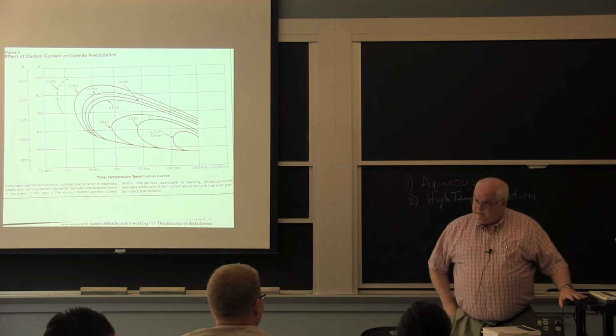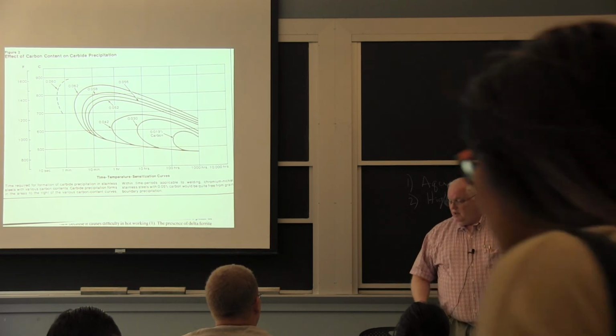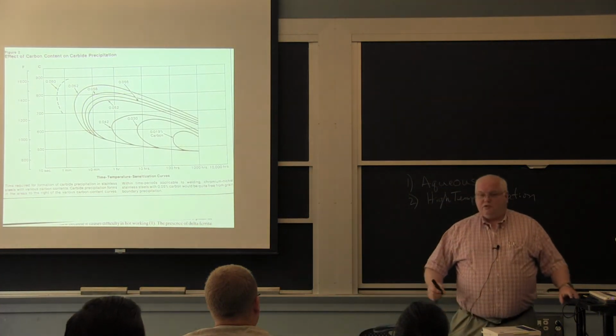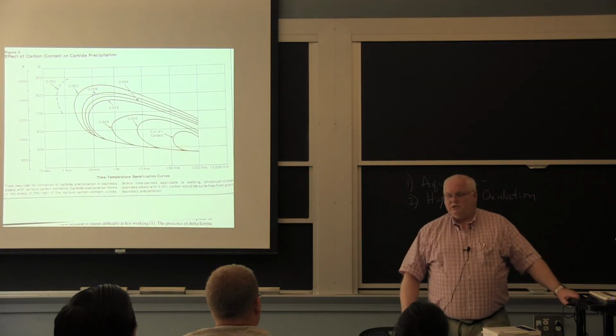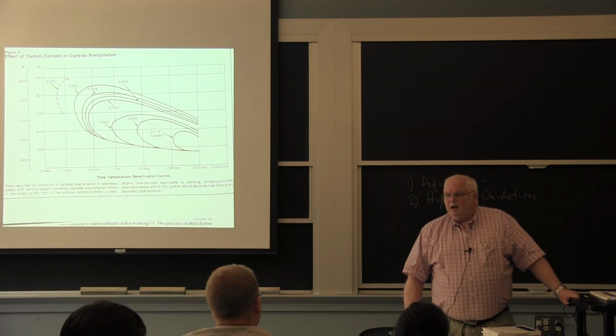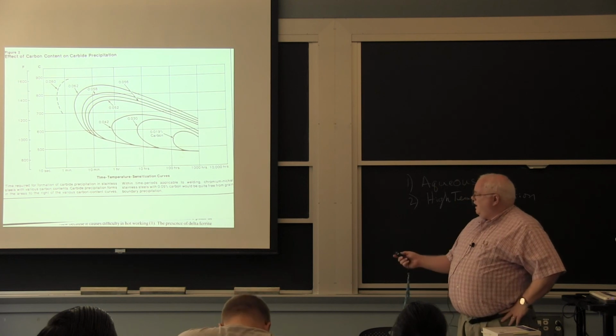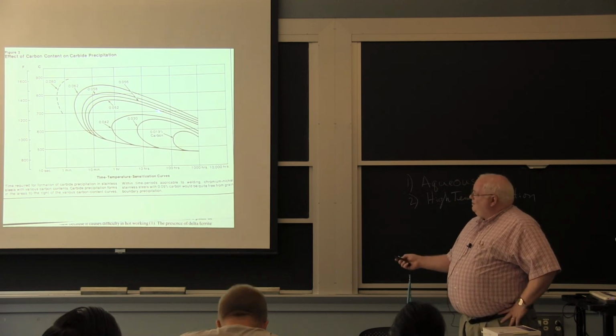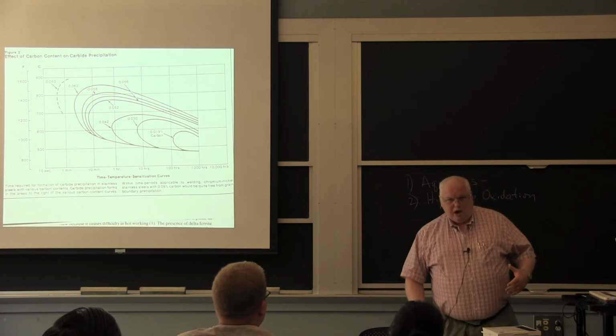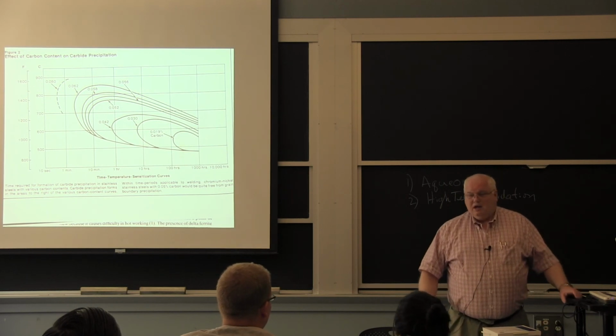There aren't a lot of chlorides in that water, believe me. And I said, no, I don't think this is a corrosion problem. And it turns out it's not a corrosion problem, it's a design problem. It's a thermal problem for the way they designed what was going through this filter. But in any case, General Electric ran into this $2 billion worldwide problem because they had stress corrosion cracking in